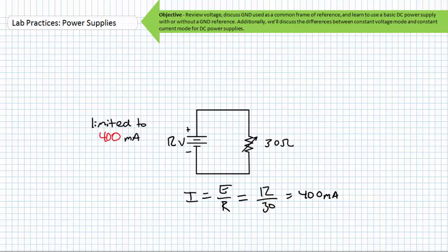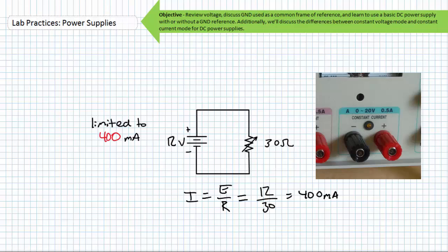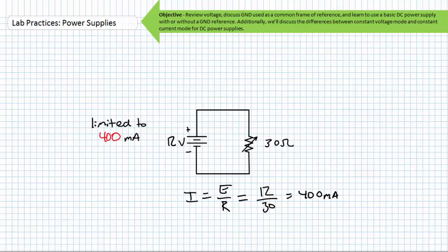Inside the constant voltage mode, current increases to the maximum with decreasing resistance. Once it's entered constant current mode, any further decreases in resistance will result in decreasing output voltage to keep the current constant. For our power supply, when a pair of terminals enters this region of maximum current, it indicates so with an LED. In the case of the A and B pair, the LED says constant current, and the fixed 5-volt power supply indicates it is in overload.